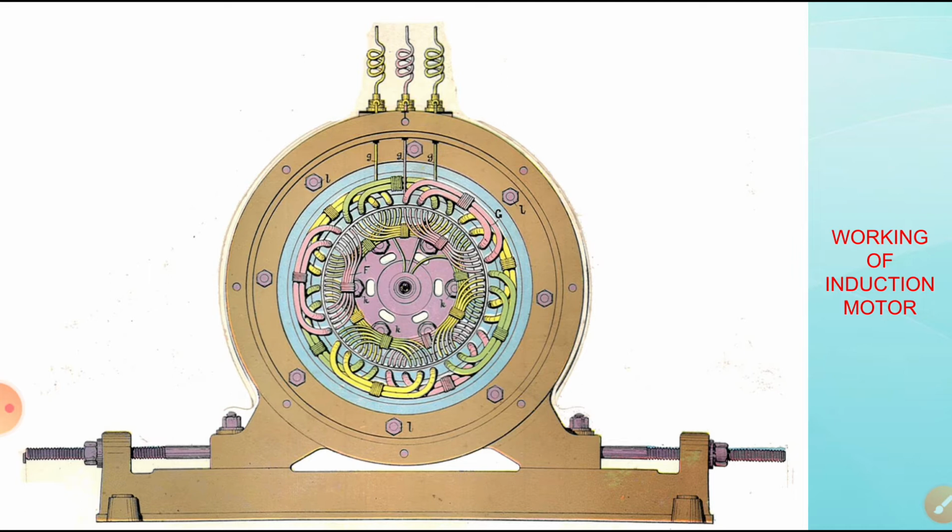Three-phase induction motors have self-starting torque, unlike synchronous motors, which are inherently not self-starting, as we have seen. Hence no starting methods are employed, unlike in synchronous motors. However, single-phase induction motors do not have self-starting torque and are made to rotate using auxiliary windings. We will see that in the next chapter.